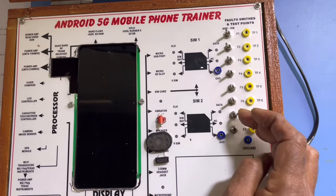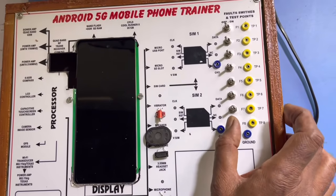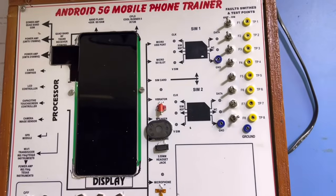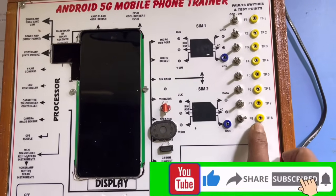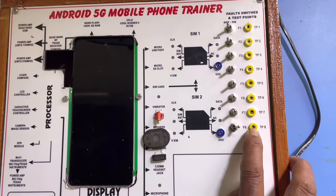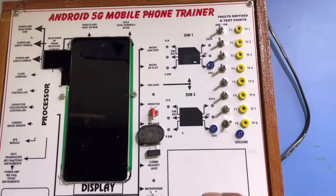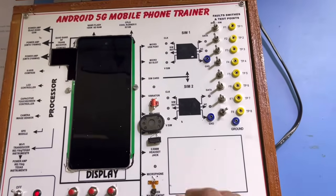In order to introduce the eighth fault, F8, take the lever of the eighth switch to the right side and the remaining levers of the switches to the left side to cut the supply of the battery section. In this case, if we measure the voltage at TP8, test point 8, the voltage will be 0. In this way, we shall introduce the various faults in the 5G mobile by the use of these various switches.